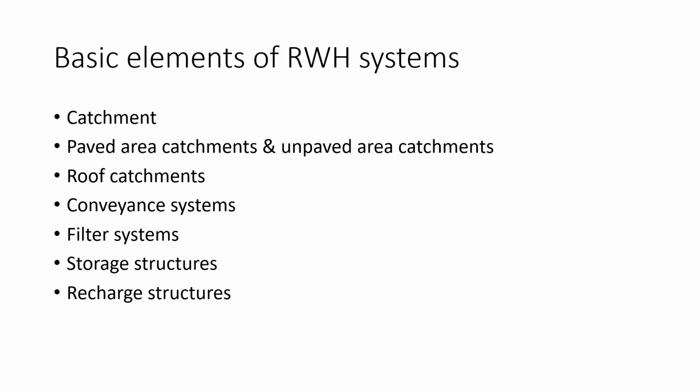Similarly, when rainwater is collected in driveways or parking areas, courtyards, or on roads, water is generally conveyed through gully traps, channels, storm water drains, and sometimes collected at the end of a natural slope. This water can be used for groundwater recharge or for non-potable uses such as gardening. The quality of water collected in these places is not as good as that of a rooftop collection. This is very important.